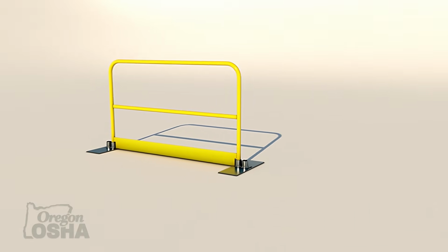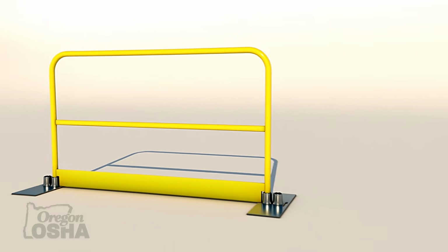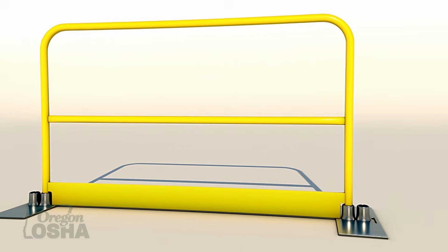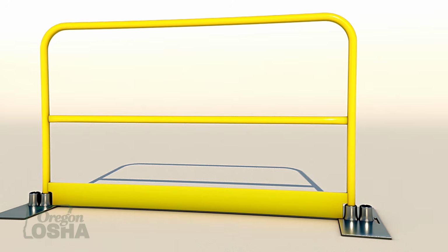Training is a key component when using fall protection systems, because even something as simple as a guardrail, if you have a guardrail system and you don't train your employee on what its purpose is, to protect you from a fall hazard that is on the opposite side of the guardrail. We've seen situations where employees use guardrails as a ladder to get a little bit higher. They need to change that light bulb that's in the corner, and there's a guardrail right there. So they stand up on the guardrail and now have exposed themselves to a fall hazard.